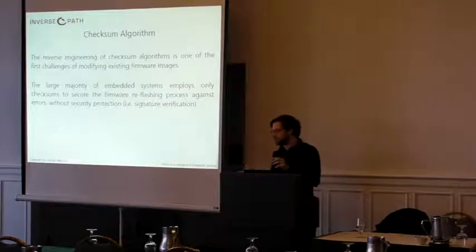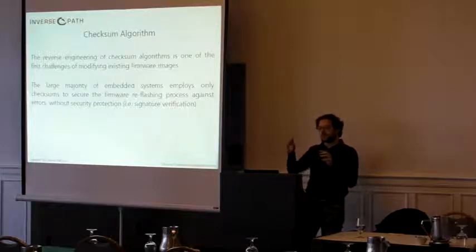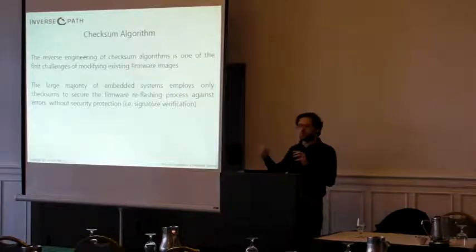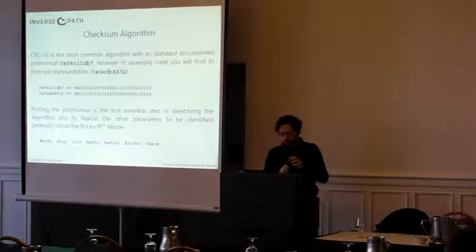And since creating collisions is very easy, you need just 4 bytes that you can arbitrarily manipulate within the firmware image. If you have that freedom, which you always have, then just do a collision and you will be much safer.